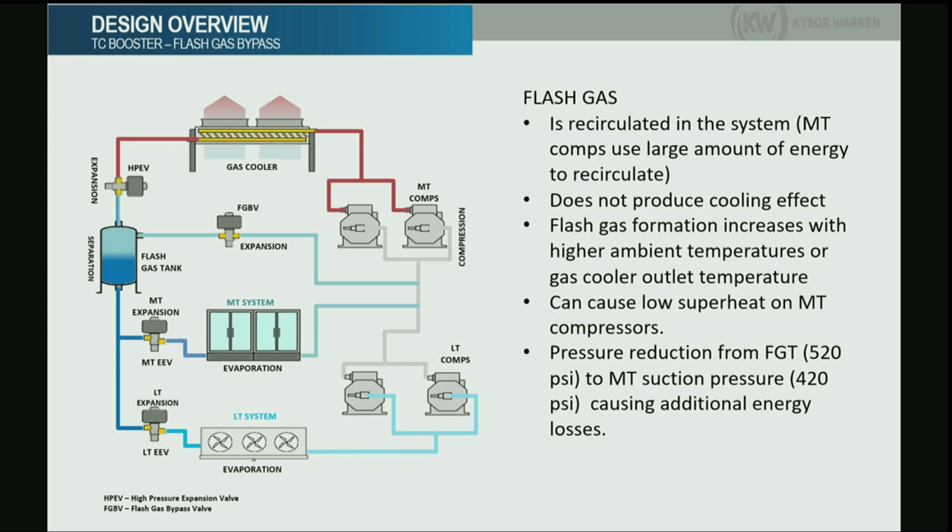You will say at least you're gaining from that if in this setup we don't have a liquid dump to offset the superheat. Actually, in the actual units, you will have different ways to maintain the superheat on the compressors. I'll show you that, but we have a hot gas injection and liquid injection in case of high or low superheat. But the flash gas bypass valve, as it's bypassing with that vapor being around 35 degrees or so, it is assisting with desuperheating the discharge gas in some sort of way.